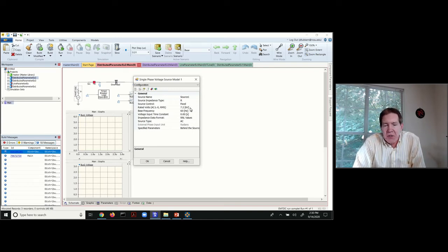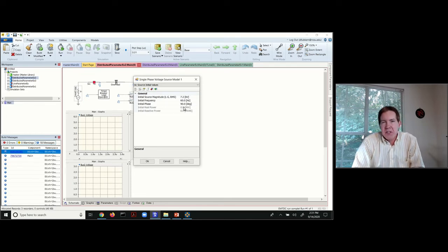I'm just putting a regular AC source in here, making use of the fact that it's not going to change very quickly. And since the default would be a sine waveform, I'm shifting this by 90 degrees so I get to the peak of the waveform.